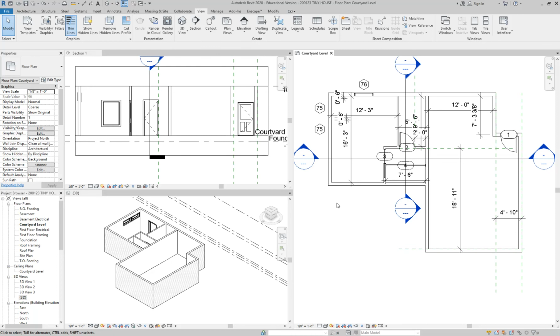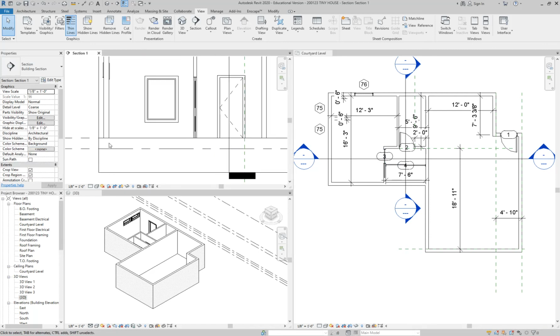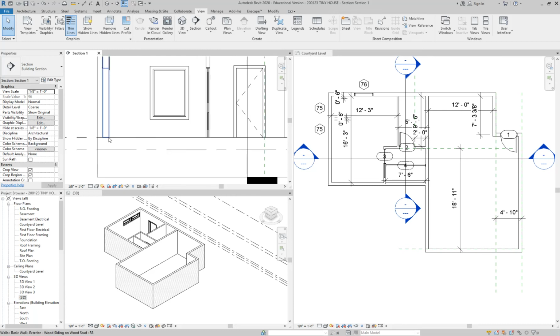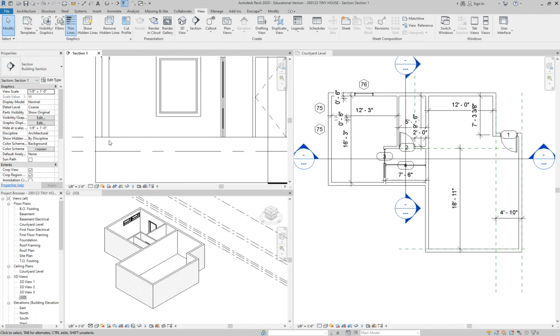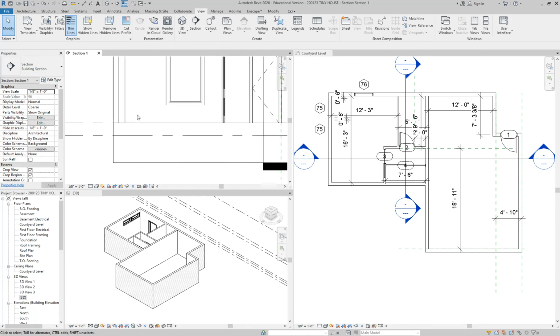So with that very long introduction, let's go ahead and draw our first bounding box, doing a floor. So before we even get started, let me look at our section. So when we draw our floor, you guys might not know this, so I'm just going to tell you. But when you draw a floor, it's actually going to come to your interior portion of the exterior wall. Do you guys see where my cursor is? So your floor doesn't come out here because usually there's like a footing or a foundation that comes up. So we're going to draw it to here.